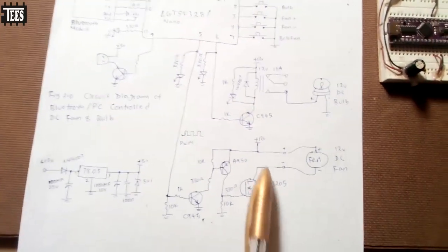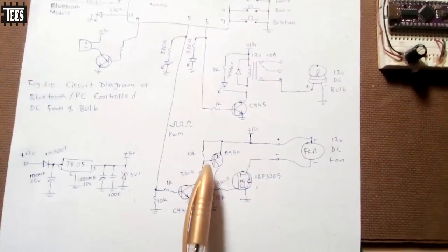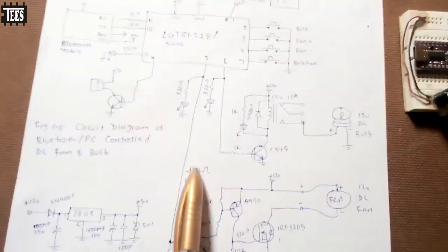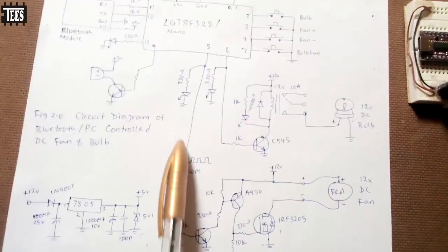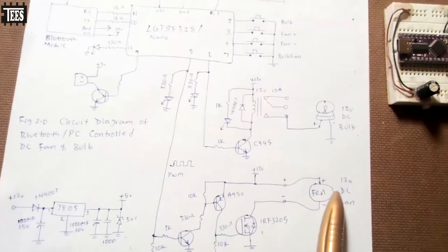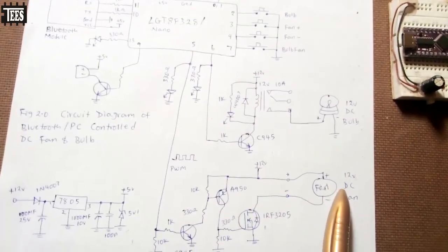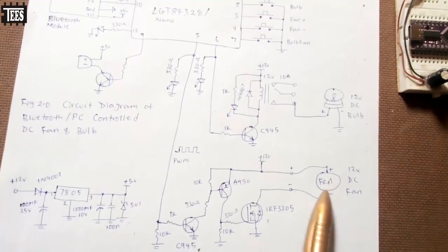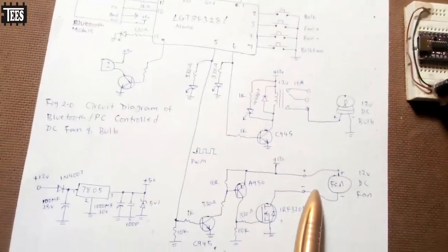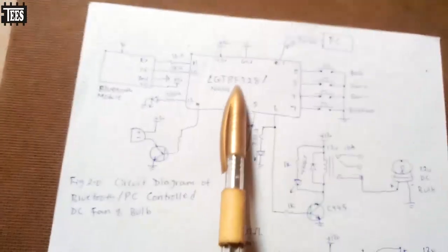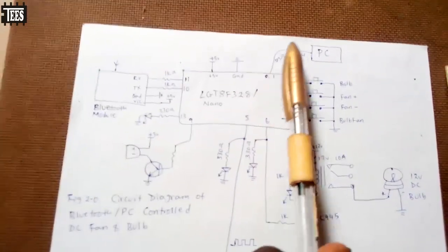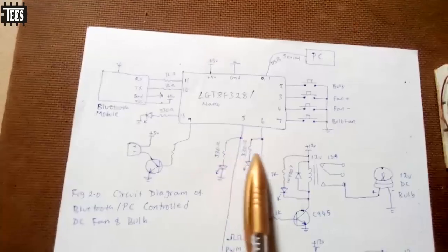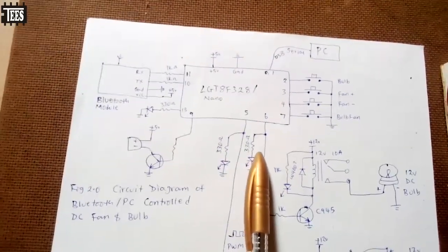But for the fan there, we need this transistor motor driver, so that I can be able to use a PWM signal. You can see this is the PWM signal. So I can use PWM signals to turn on the fan, increase the speed to the maximum, and then reduce the speed to the minimum, turn it off. So that's our aim. Our board is going to be connected to the computer. From the computer keyboard, we can issue commands to control pin 5 and pin 6.